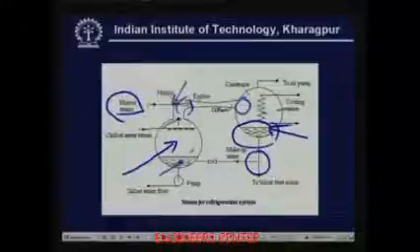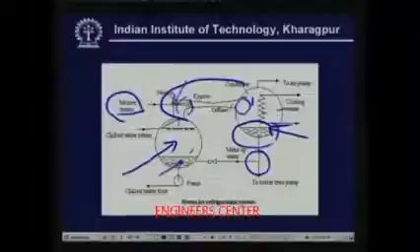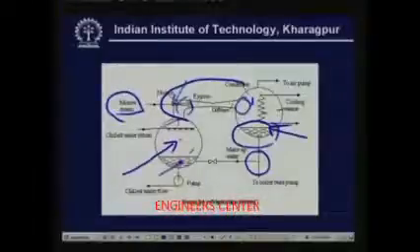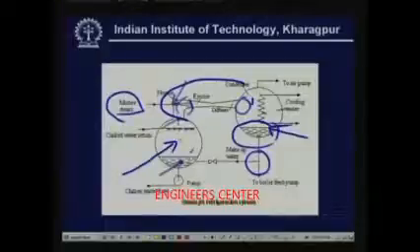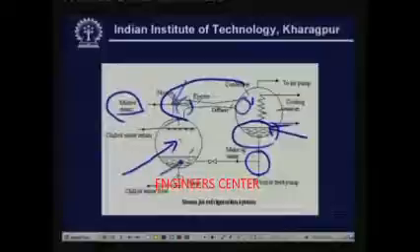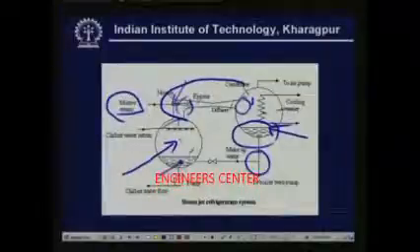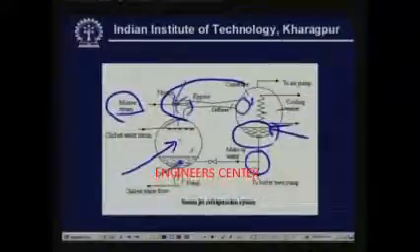As you can see, we don't use any mechanical compressor here. The mechanical compressor is replaced by a combination of a nozzle, ejector, diffuser and so on. So this is sometimes known as an ejector refrigeration system. The principle of the ejector was actually used in the beginning to pump out air leaked into the condensers of power plants. So this is the first application of ejectors. Later the same principle was extended to refrigeration systems.